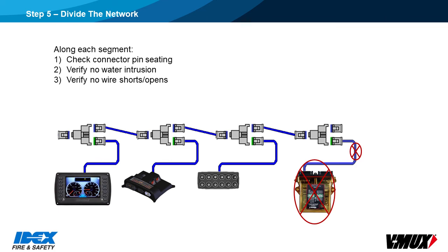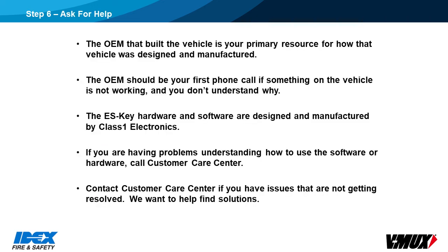Check ground wires to all modules. A module with a bad or missing ground can appear to be operating correctly but can cause inconsistent communication throughout the network.